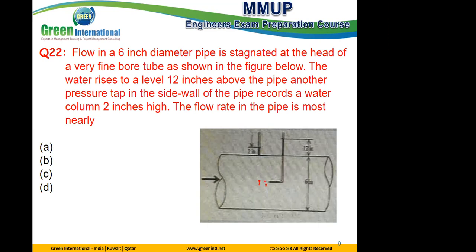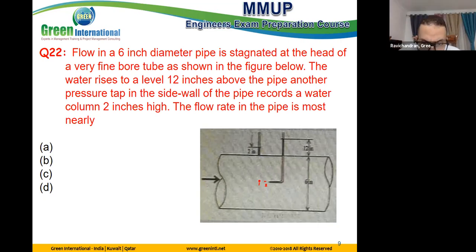No, but point 2, where you have the pitot tube inserted in the mid center of the pipe, is taking the velocity or the pressure from the center of the pipe, isn't it? Whereas point 1 is only at the corner of the pipe, where due to the resistance of the surface, there is very little velocity or pressure.